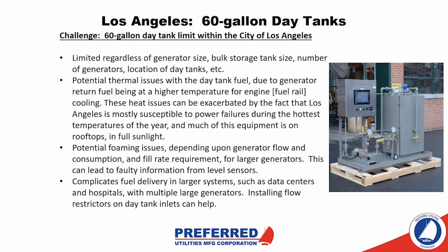Some of the things that can arise on the project design are potential thermal issues with the day tank fuel, especially on larger generators. Generators will flow quite a bit of fuel, and they tend to return about 2/3 of it back to the day tank. When that fuel is returned back to the day tank, it could be returned a little hotter than the fuel that was in the day tank to start with. So as time goes by, the fuel in the day tank can actually rise as far as the temperature goes, and start creating issues in situations like hot days, etc.